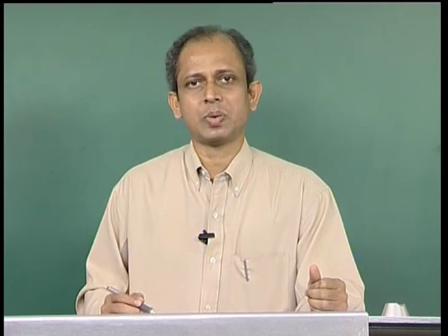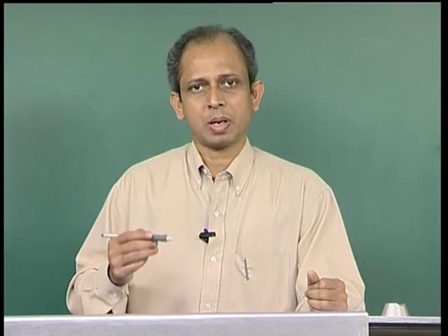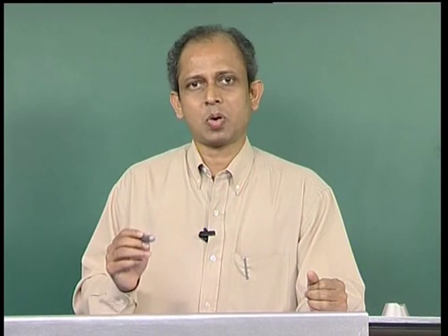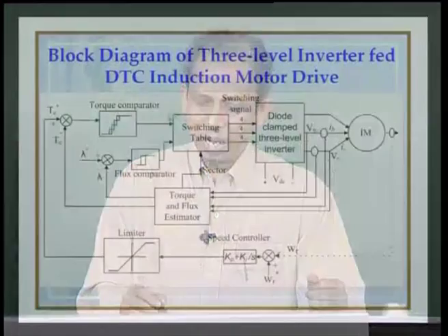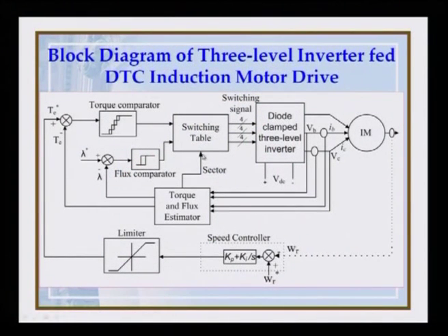The sector information will help us apply the appropriate voltage vector to the induction motor. So, this is what we have here, and then the output of this is the voltage vector, and when we know the voltage vector, we can find out the switching signals.